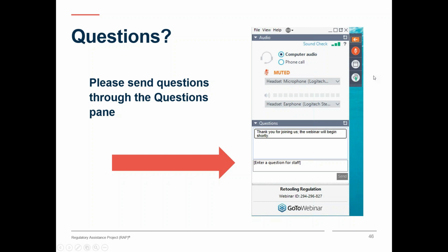EV chargers draw a lot of power for a few hours, and you can control when those hours are. If costs are assigned to the hours when they're incurred, when they provide service, the off-peak hours will have low-cost resources providing service then, perhaps sun in the middle of the day or wind in the middle of the night. And people with electric vehicles can take advantage of that if the cost allocation is to time periods, and then the rate design takes those time periods into some account.